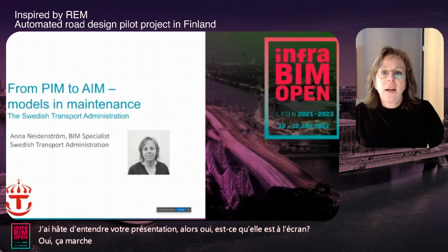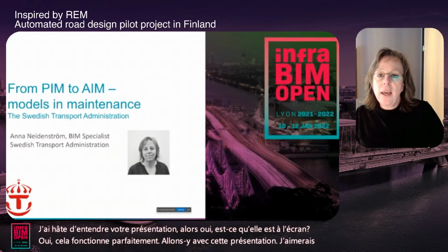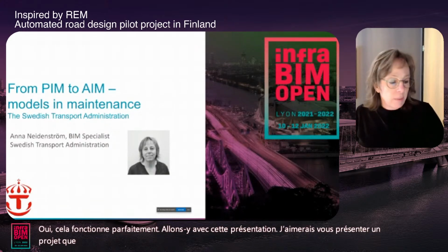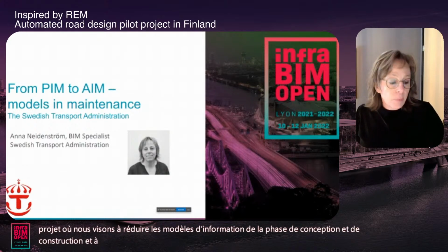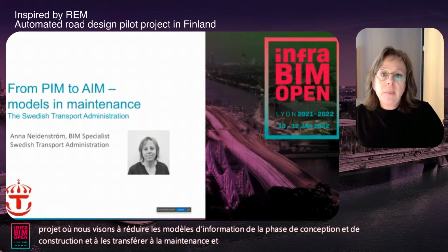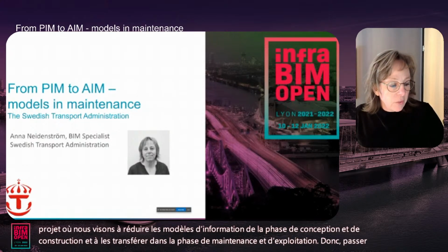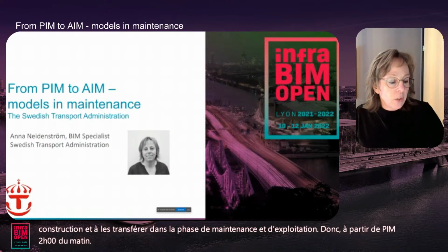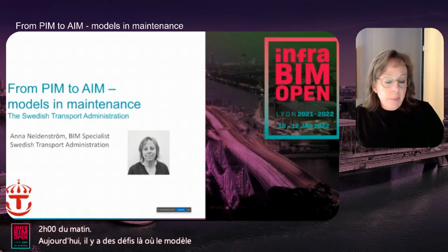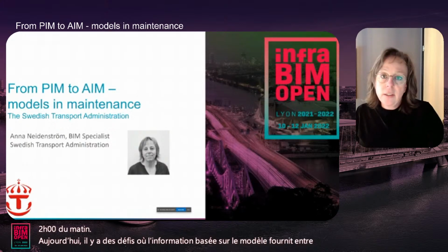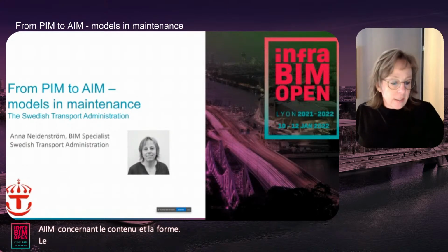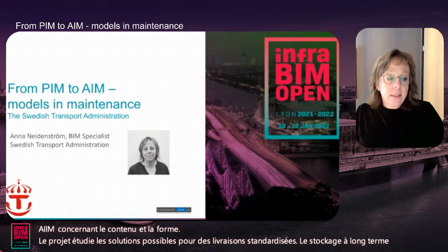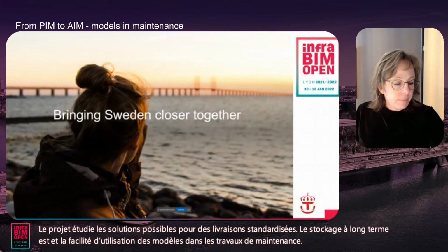With this presentation, I would like to introduce you to a project where we aim to reuse the information models from the design and construction phase and transfer these into the maintenance and operation phase. So going from PIM to AIM. Today, there are challenges with model-based information deliveries between PIM and AIM regarding content and form. The project investigates possible solutions for standardized deliveries, long-term storage, and usability of models in maintenance work.